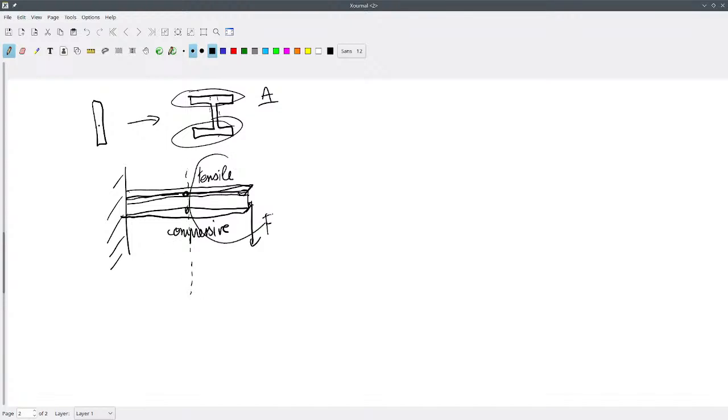Also, one of the things we sometimes do in physics is we'll just consider only this half of the I-beam as a system, and then look at what force is operating on that I-beam here. So it's a tensile force on the outer part of the I-beam. The tensile force will be in this direction, so that's our F perpendicular. At the bottom part, the compressive force will be in this direction, so that's my F perpendicular.